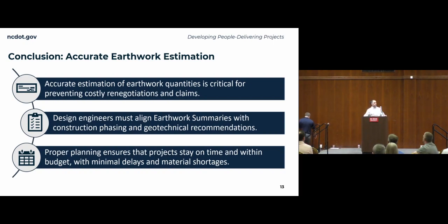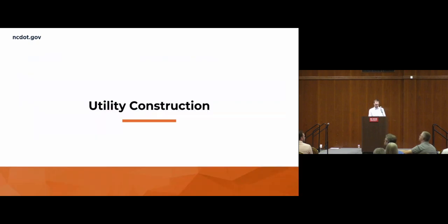Yeah, I would just say, sort of to Liam's point, when we were talking about phasing for unclassified and borrow, we also have to remember that in some of that phasing for unclassified, we're accounting for some of the concrete material, some of the sidewalk, curb and gutter and so forth, and even the rock material. So when he keeps talking about the top 3 feet, it's exactly how we're using some of that material and where we're wasting it. A lot of that plays into the phasing and what we're looking for, and some of the other items I'm going to talk about will also relate to the phasing issues.